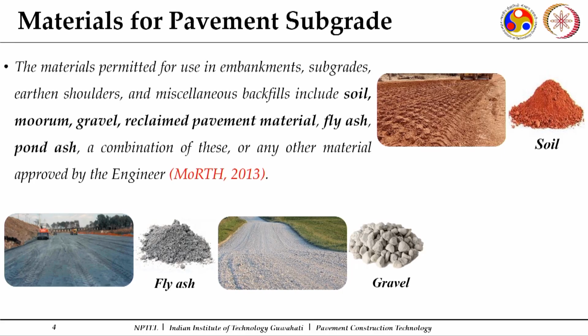As per MORTH 2013, the different materials which fall under the category for use in pavement subgrade construction include, it says, the materials permitted for use in embankments also. Normally, wherever any filling is required to raise the level of the ground, we go for the embankment construction first, thereafter the subgrade construction.